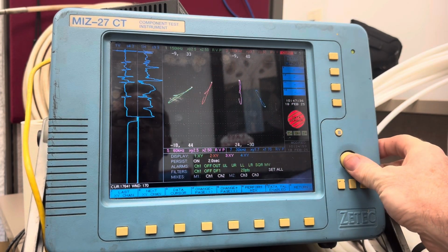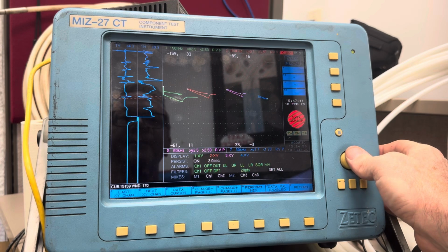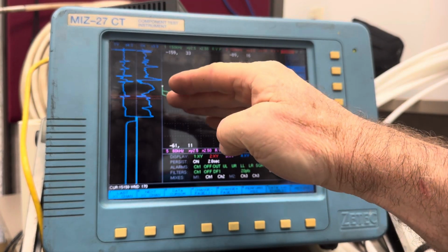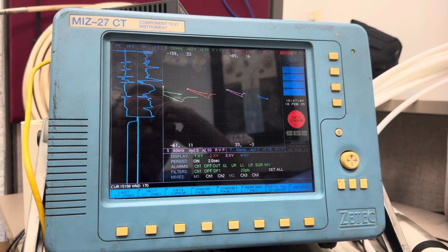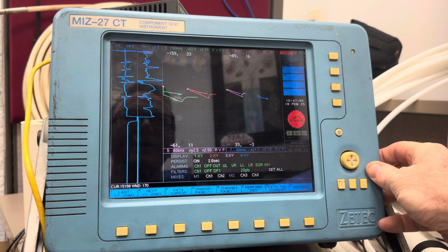So just to run through these real quick again. There was our crummy looking 100%er. Low phase. Now, keep in mind that the amplitude and the phase of this particular signal, and this is a tiny, tiny through-wall hole, is a weighted average of all of the disturbed eddy currents at every depth.